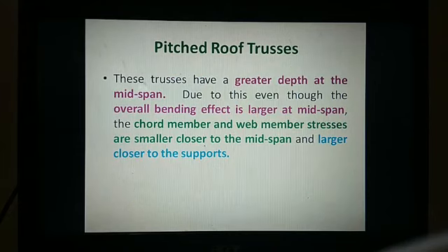Again, these trusses have a greater depth at the mid span. When you provide a proper pitch, the depth of the truss will be more at mid span. Even though the overall bending effect is larger at the mid span, the top chord and web member stresses are smaller closer to the mid span and larger closer to the supports.